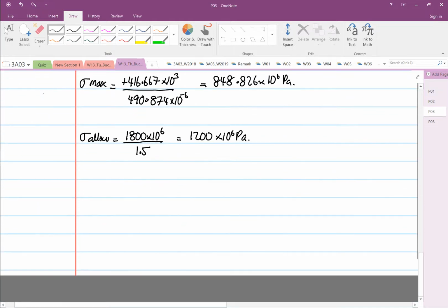So what we realize, therefore, is that stress max is lower than stress allowable, right? So cable AC will not fail.